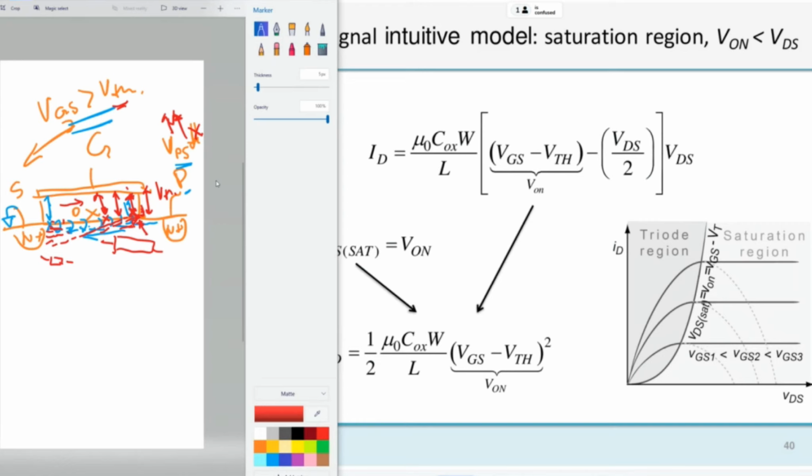So if I increase further beyond this point, the voltage between gate and drain will be less than the threshold voltage, which means that I cannot maintain the channel in the vicinity of the drain. Of course, I will not follow this equation, because I cannot create charge densities which are negative. Physically, the charge density is just zero. So it saturates to zero. Then this means that the channel resistivity or conductivity of the channel will saturate to a certain value.